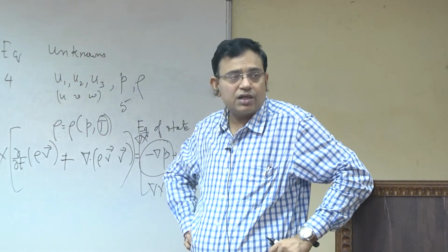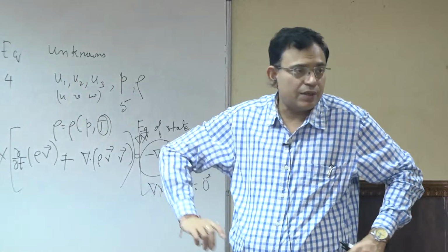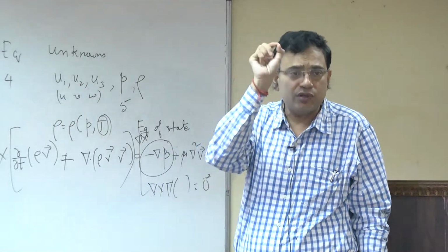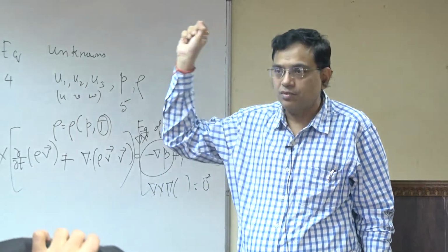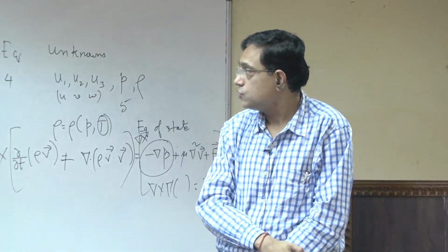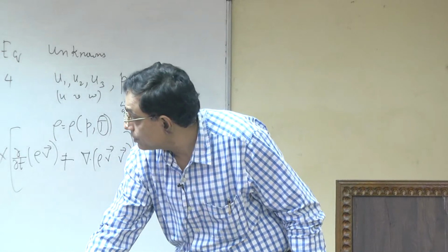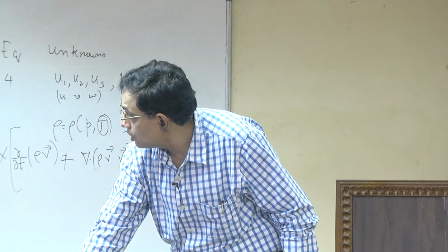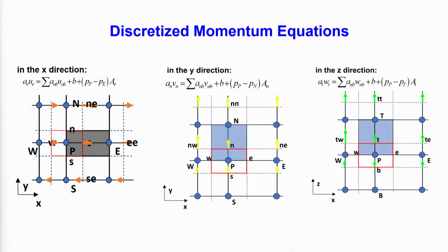but staggered grid will mean more bookkeeping. That means you need to have a separate accounting for the pressure grid points and separate accounting for the velocity grid points. So, how do you stagger this? Maybe let us go to the next one. If you consider now these diagrams, it will tell you how to stagger this.